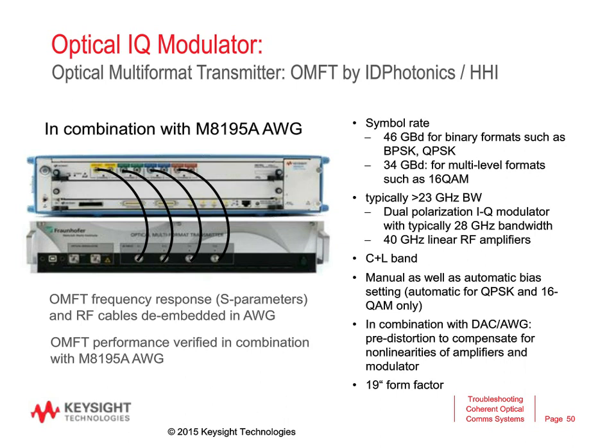We have dual polarization IQ modulators inside. Amplifiers are used up to 40 gigahertz inside. There's manual and automatic bias control available inside the module.